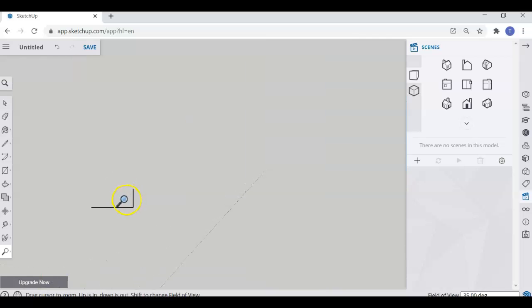All right, now if I zoom in here, I can see the stud I'm building, at least looking from the top down. I've got to go another 3.5 inches, because remember a 2x4 stud is actually only 3.5 inches wide and 1.5 inches thick. And I've got a rectangle that represents looking from the top down on a stud.